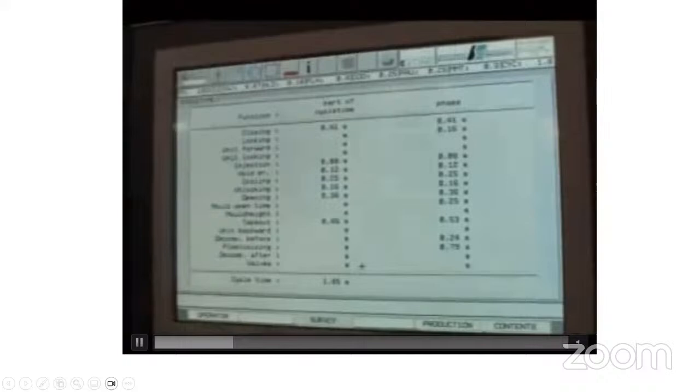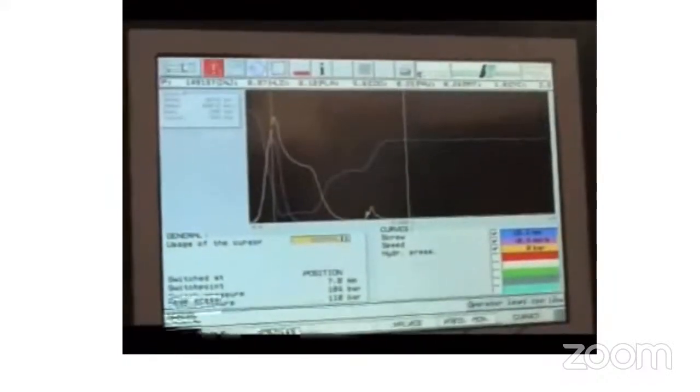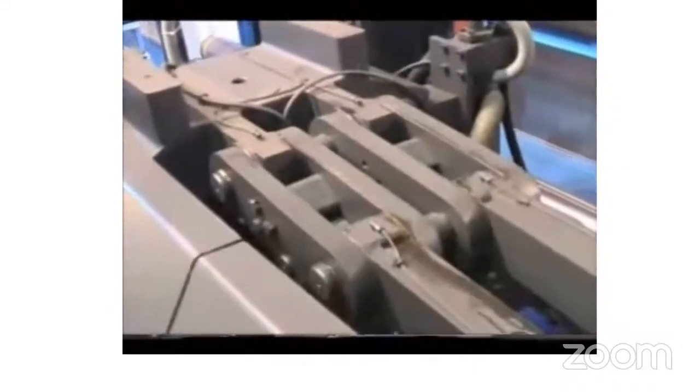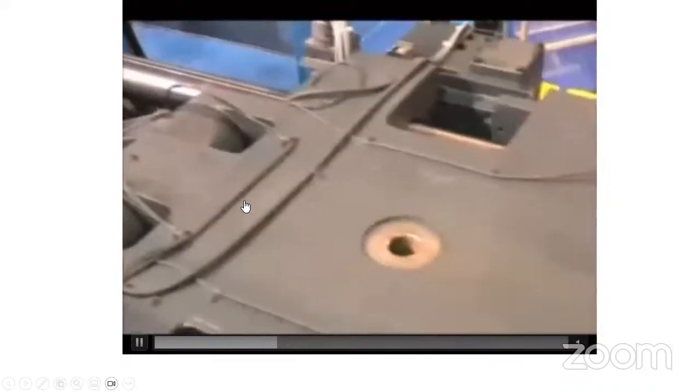There is a screen board, you will get the microprocessor machine, and you will get all details there. See, these are the two impressions, or two articles, you are getting simultaneously. And this is the automation, right? The robot will take the two articles immediately from the opening of the mold, and it will just place them there, right? And I told you, the double toggle system.